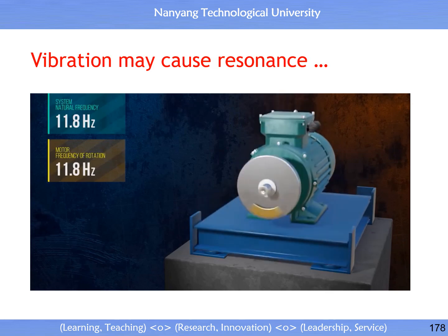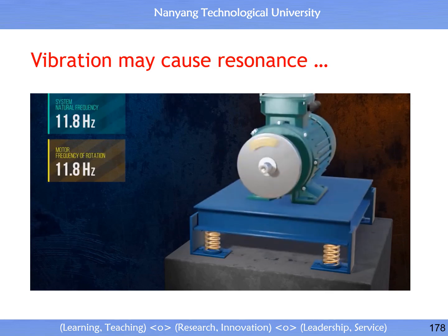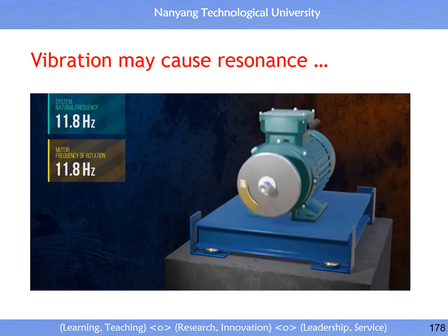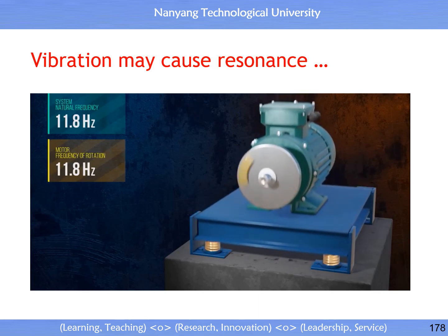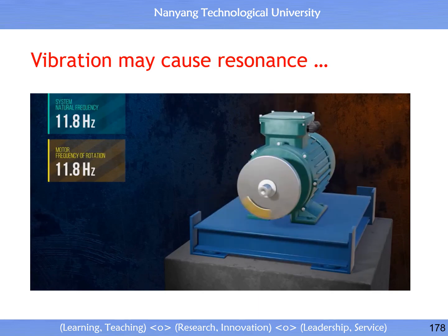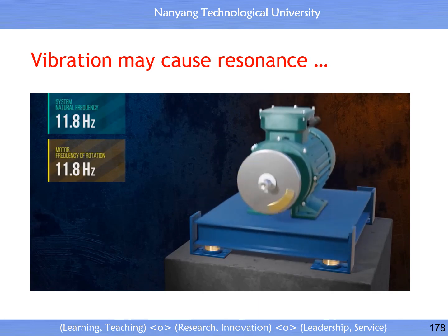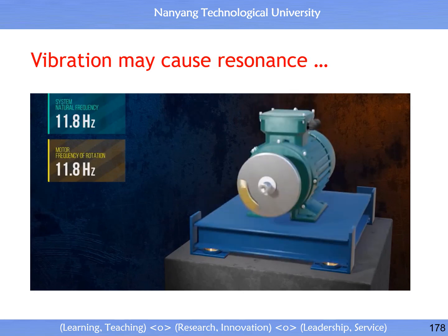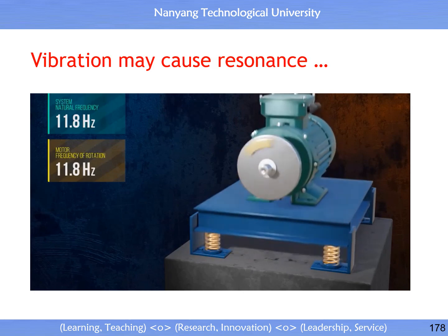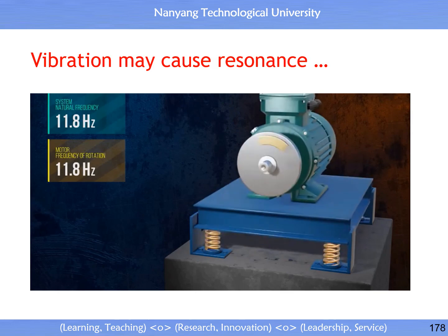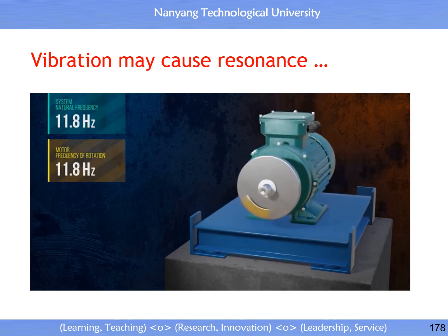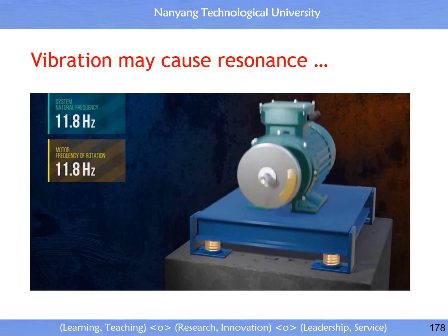It's one of the reasons it's so important to be able to calculate the natural frequency of a system. If the natural frequency of a bridge matches the frequency of wind loading acting on it, or of pedestrians crossing it, the results can be catastrophic, particularly if the structure has little damping. Devices called tuned mass dampers are sometimes installed in buildings and bridges to control the dynamic response at resonant frequencies.